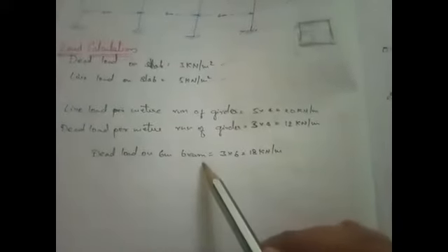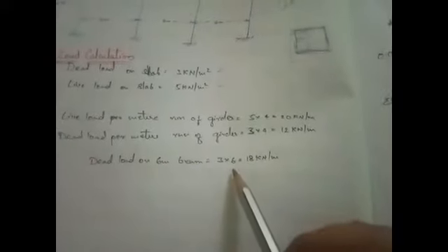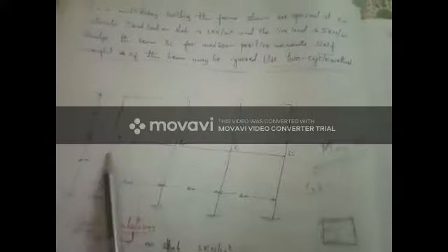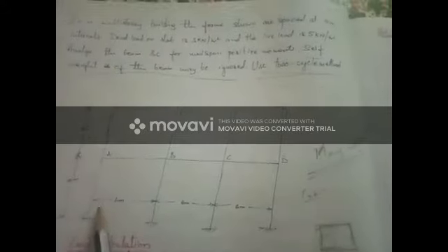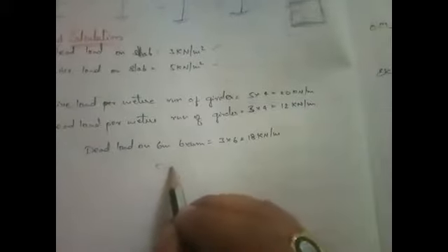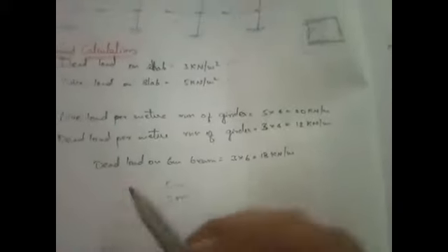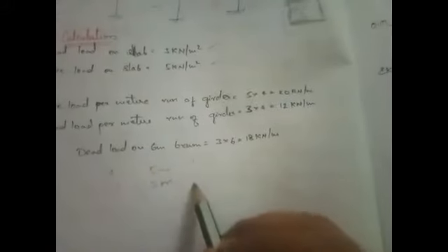So beams also you will be calculating dead loads on beams of 6 meters span. So you can check that all the beams are of same span, that is 6 meters, 6 meters and 6 meters. If we have a separate beam which is of 5 meters or 3 meters, then we are supposed to calculate the dead loads for them as well.